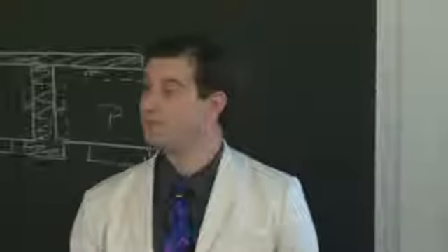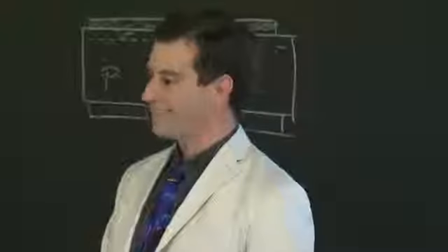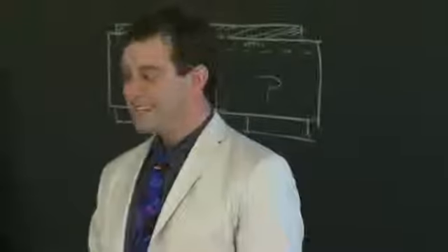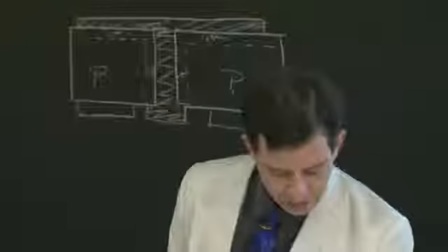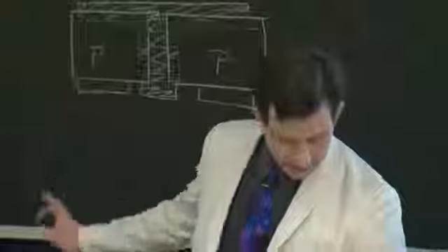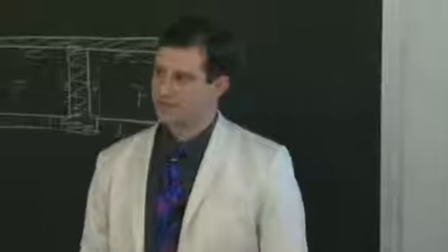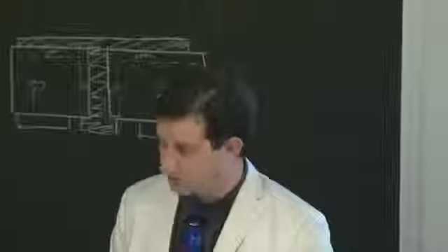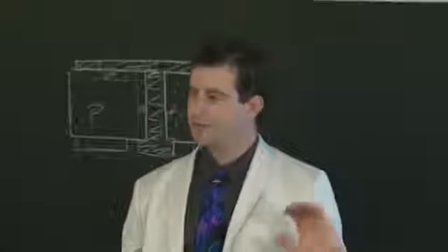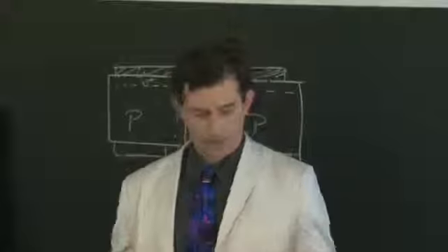Yep, Omar. The First Solar panel is a lot smaller than that panel up there. Is there a reason why First Solar goes with smaller cells? Yeah, so why is this First Solar module, the FS Series 3 module, a little smaller than some of the crystalline silicon modules? For thin film deposition, especially for the closed space sublimation process that First Solar uses, you're limited in terms of the deposition area by the uniformity of deposition over a large region.